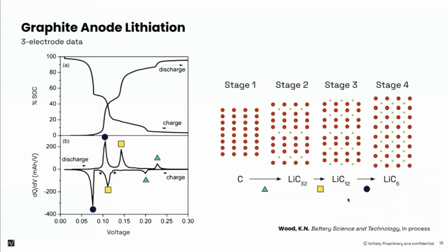There was also a question about smoothing. That's a good question. A lot of times when you plot DQDV, depending on how the data was recorded from your cycler, if it's recorded in time, there has to be a smoothing process that is done. So depending on the resolution of your cycler, different smoothing levels will work, usually 1 to 10 millivolts.